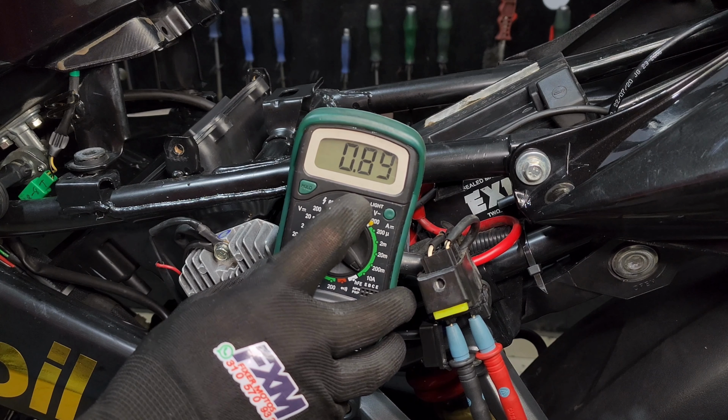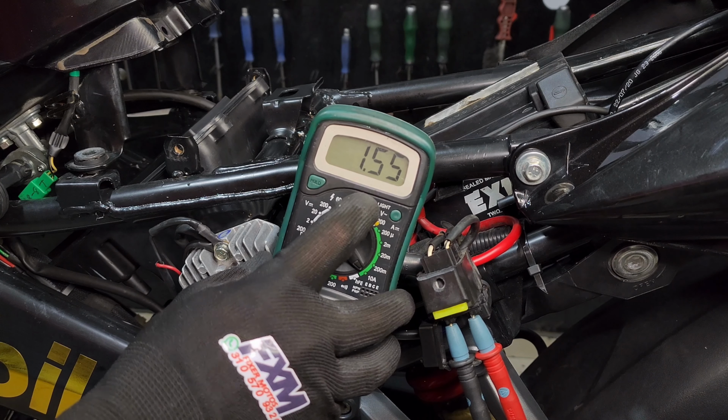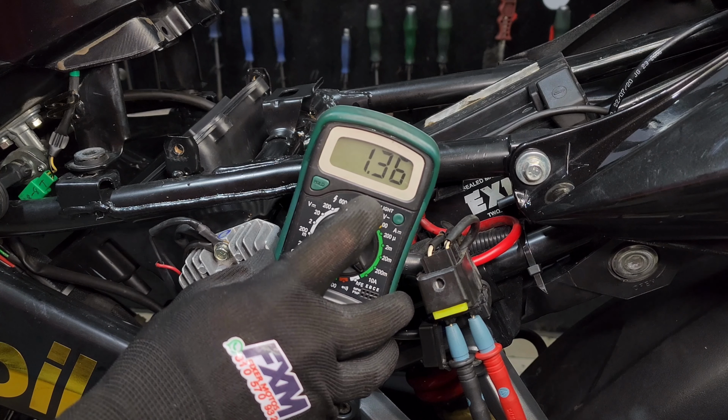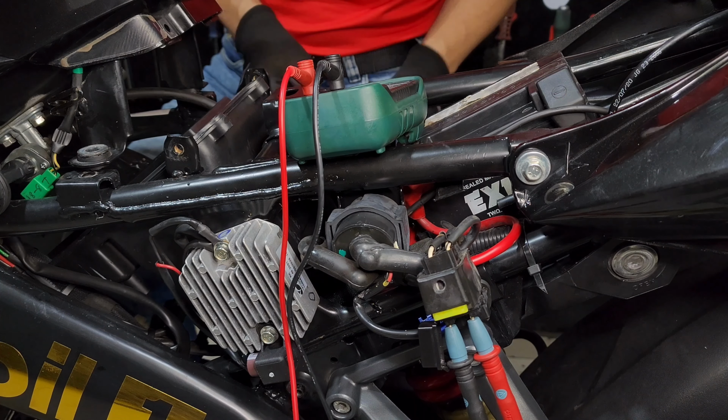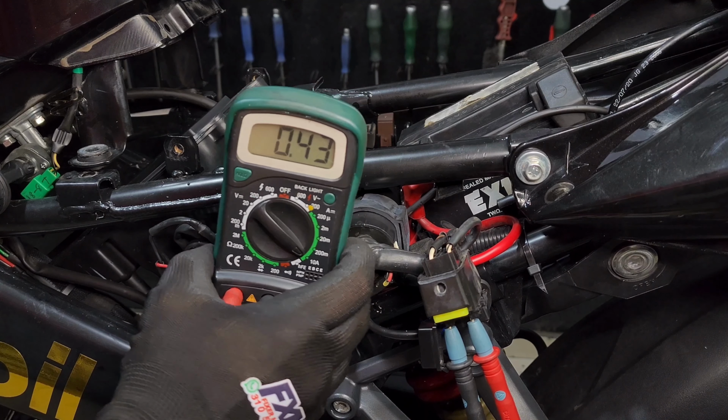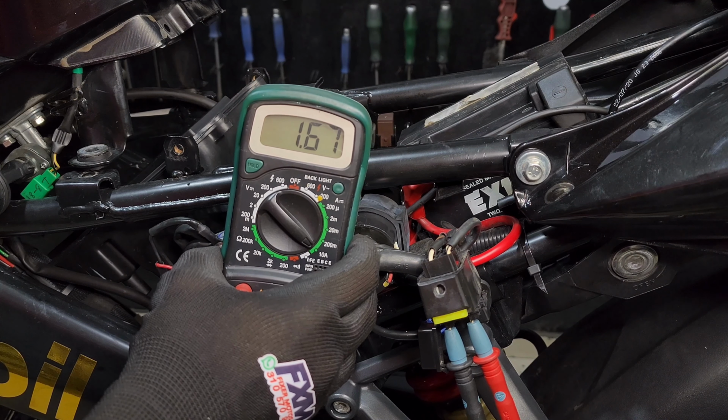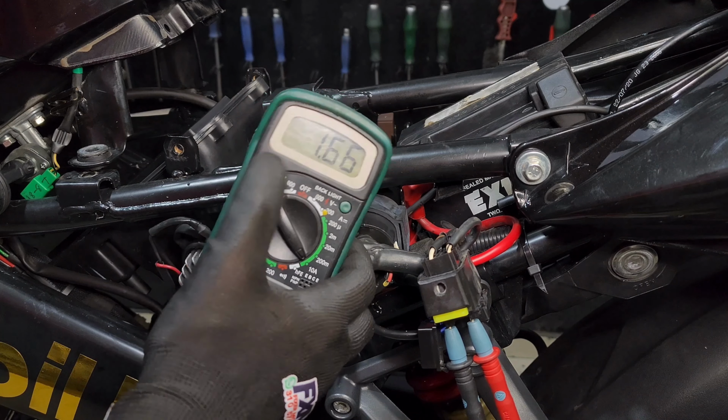So to take a current reading, what I'm going to do is direct the current that goes to the turn signals. That is, I'm going to suspend the flasher. Ready, so what I did was bridge the orange cable with the brown one, and there I have the turn signals activated.